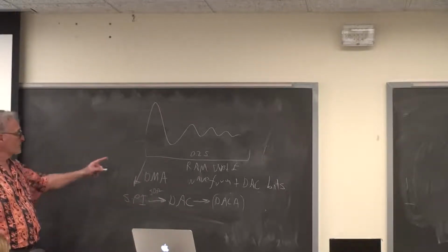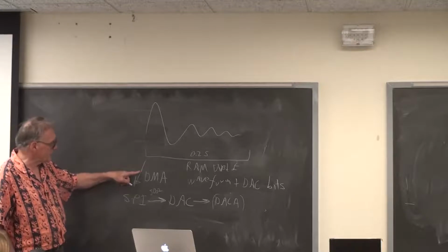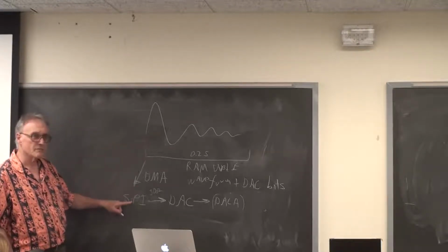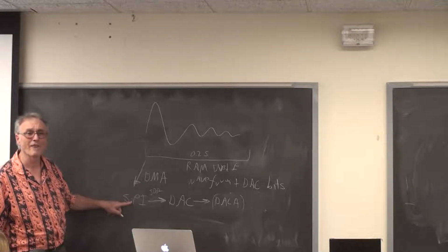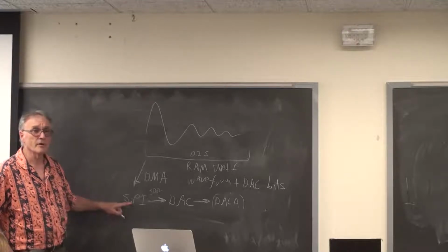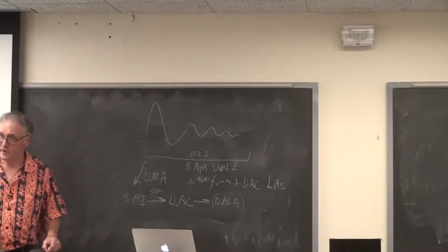In this case, the DMA channel is going to copy this table into the SPI transmit buffer. Every time you copy to the transmit buffer, the SPI auto-transmits.